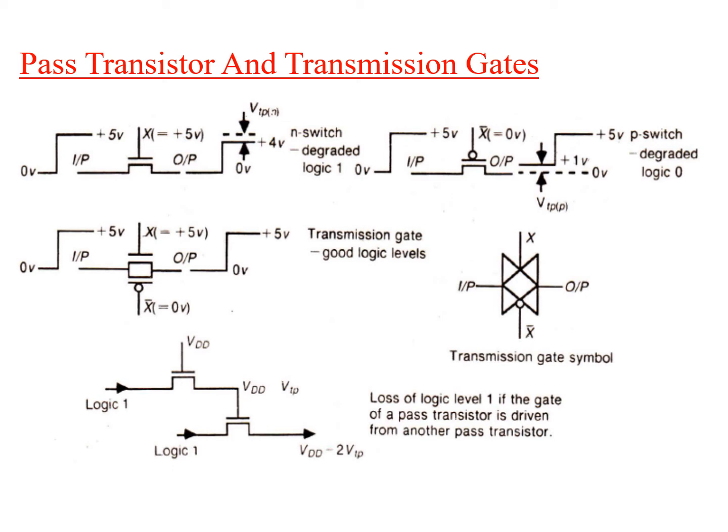Now if you combine two NMOS like what you can see in the third part, here the gate terminal of this NMOS is connected to the output of this NMOS, so that logic 1 is applied at both inputs of your NMOS. But the output at this end will not be what you expect, since it is an NMOS, there will be degradation of logic 1, and that degradation is carried over to the gate terminal of your next MOSFET.